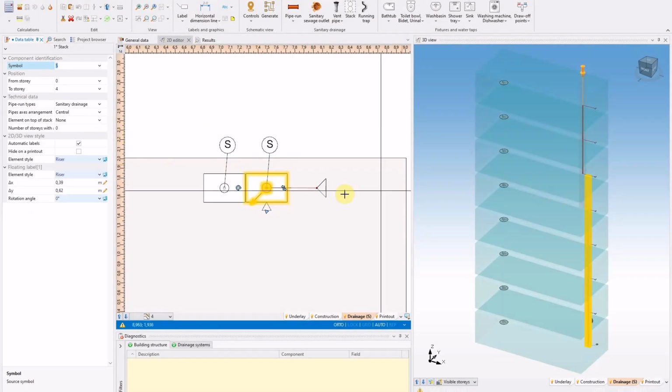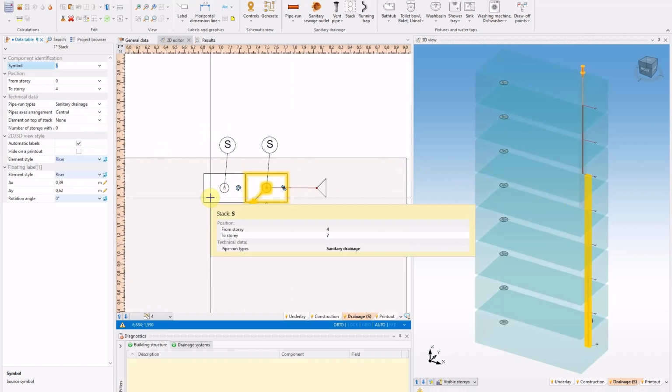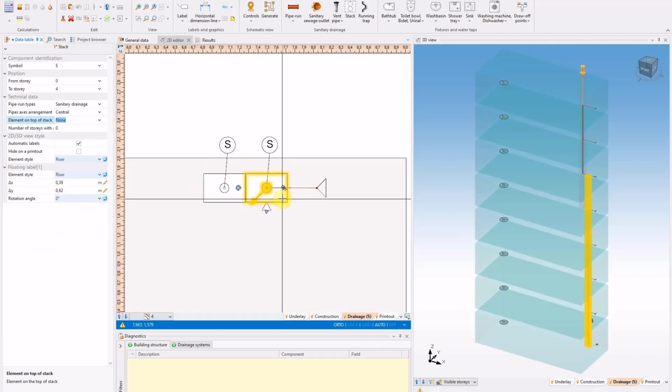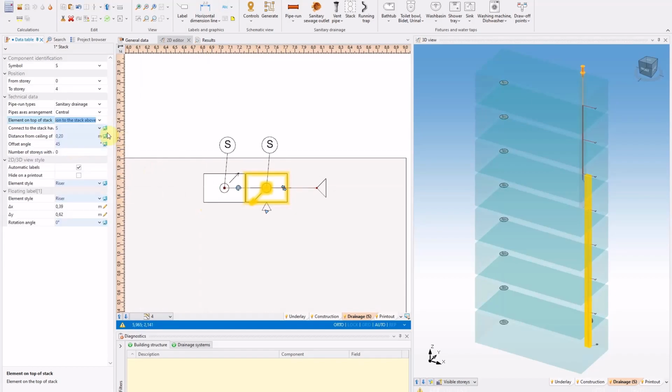There are situations where parts of the stacks located on different stories do not lie above each other, but must be deviated. To achieve this, while keeping both parts as one vertical in the results, create two shifted stacks whose ranges span one common story.